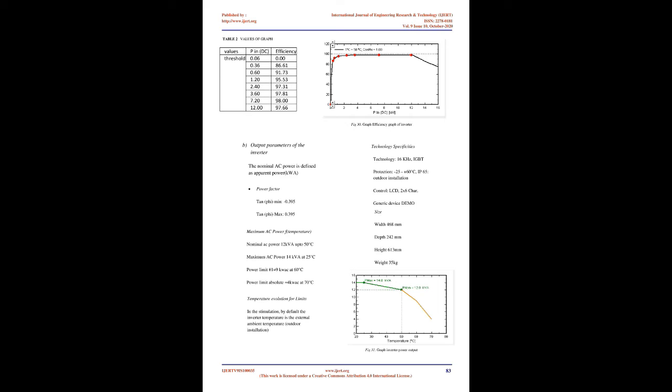Reverse characteristics. Single cell reverse characteristics. Quadratic factor BREV, 3.2 mA/V². NB. This reverse parameter is only used in the framework of the array behavior special tools, partial shading on modules. Its value is not essential and can be taken as the proposed default. Number of bypass diodes, 3/module. Diode direct voltage, -0.7 V. Diode maximum current, 0 A.